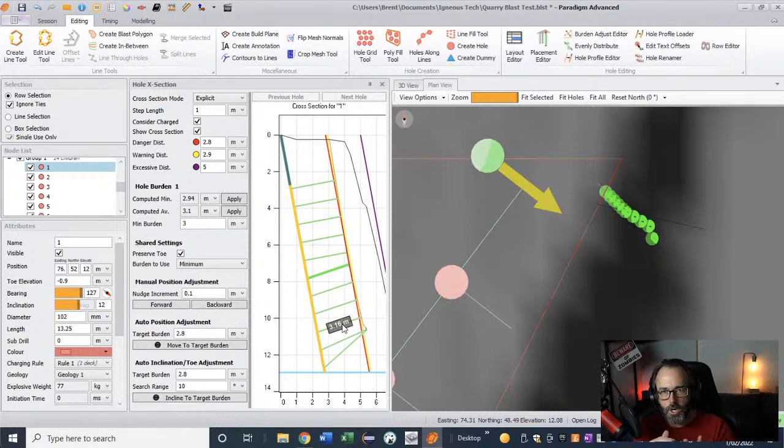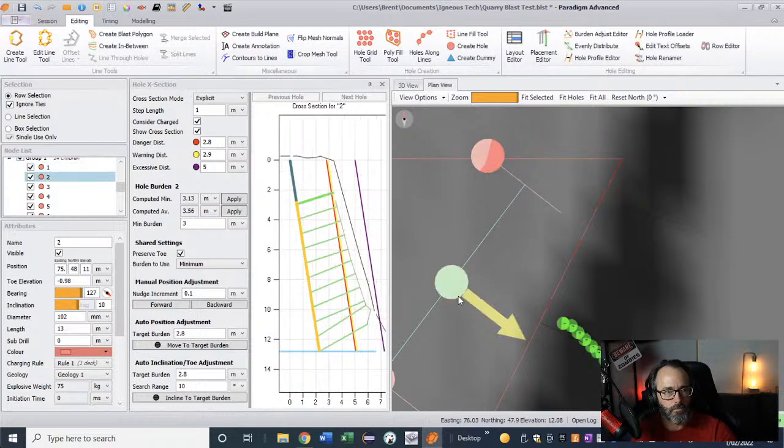We would alternate the angles and adjust it, and in your contract with your driller or your site-based driller, this would be a key aspect of their KPIs, to have zero or minimal deviation on their face, which means they need to take time drilling it. They need to drill appropriately for each of the rocks. So pretty easy.